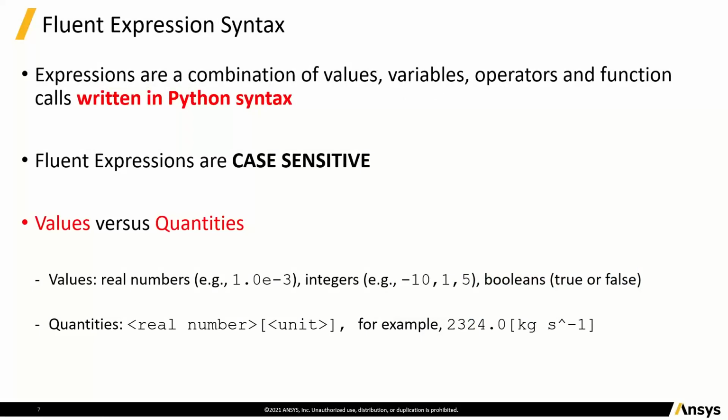So let's start going through this. I'll assume that you're new to expressions, so I'll go through the basics so that everybody on the webinar will get to see the basics. There's lots of documentation online now. So the first thing to know is that these are written in a Python syntax. And with that comes an enormous amount of power. It actually means we can do lots of things here that we can't do in CFX. And I'll show some of those in a moment. They are case sensitive, just like pretty well any language.